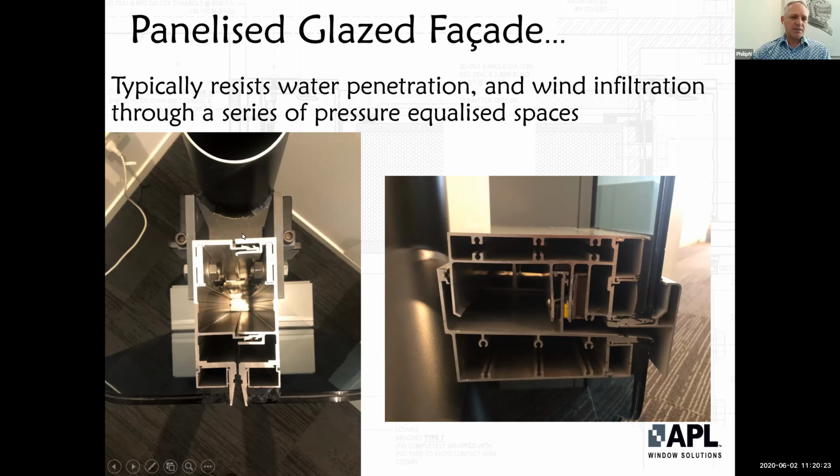It's like a seismic joint, and this is also a pressure equalized space. So any water penetration through this area drops down into this split transom, or in some cases a sill tray. So that's how it deals with water penetration and air infiltration.